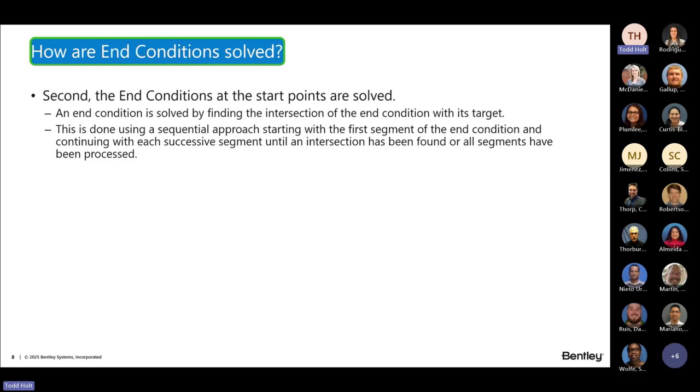And then throughout the end condition, from that crossing point to the existing terrain, for example, if it finds that target, it's going to solve depending on how we have those properties. And it's going to go through and draw each of those end conditions, drawing that end condition out as we're placing it.